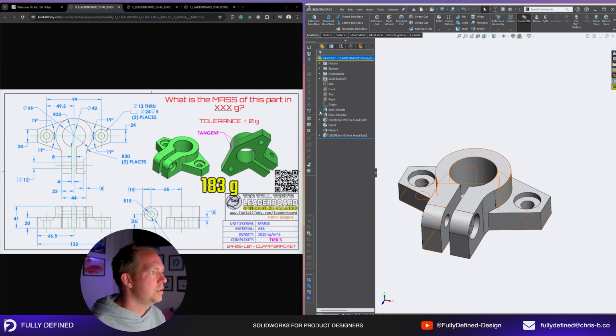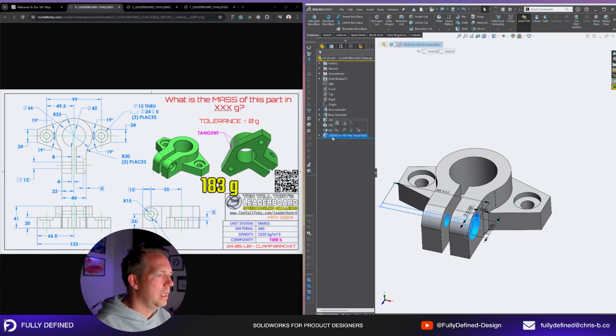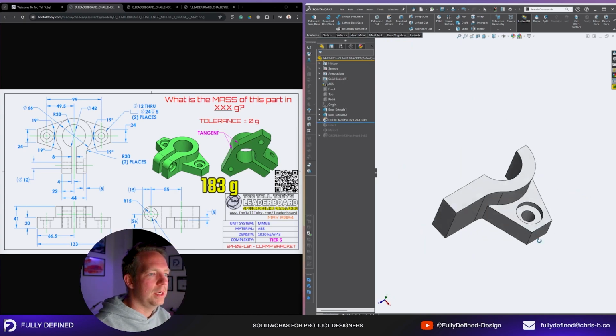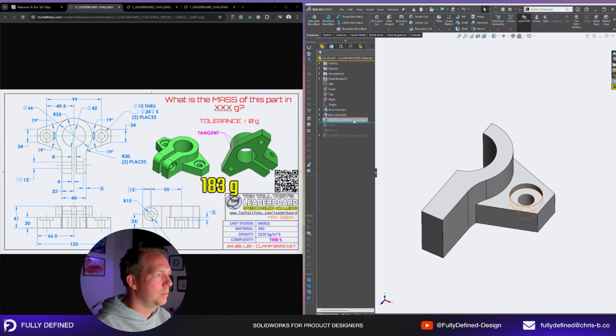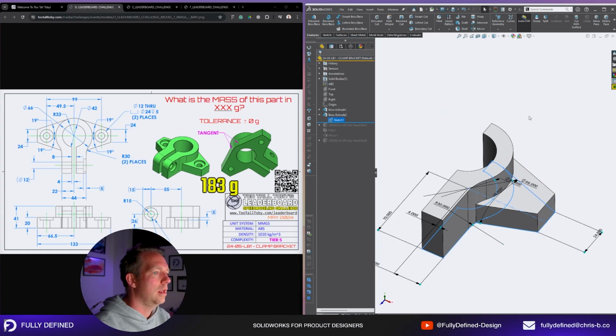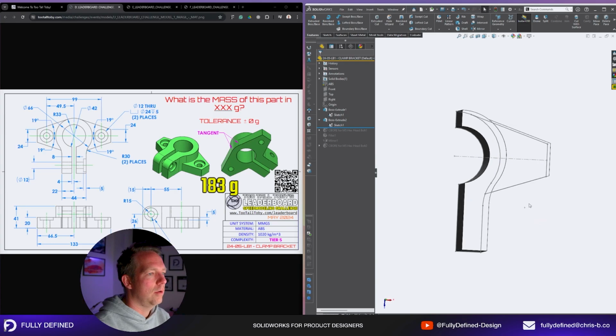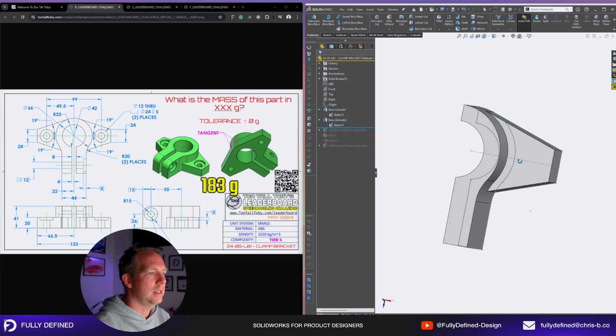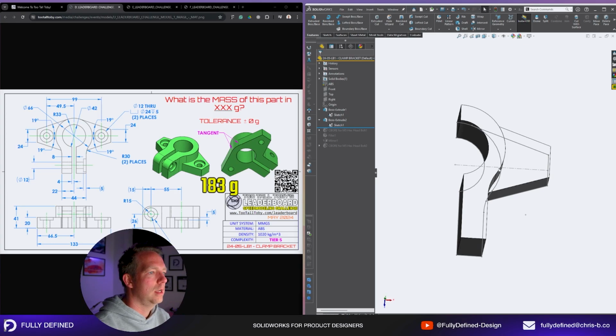Beautiful. All right, so efficiencies with this model, I think a lot of it, I think the counter bore here, the mirror here, and the fillet is all correct. Do that all first up, so park that. So it's this element here, that counter bore is probably the quickest way to do that, but perhaps finding the location instead of doing that dimension, if we can reference something in an earlier sketch to locate it, that might help. Now this is pretty quick. It will be one sketch profile. However, we want to clean that up, so we only have to select once.